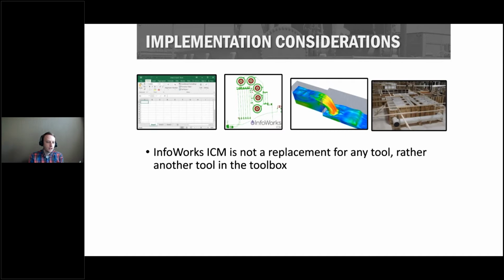I've got 4 here, but there's probably more. Oftentimes we'll do hydraulic design with a spreadsheet of some sort. There's also more sophisticated stuff like CFD modeling, or even, like this far right image shows, physical scale modeling. Where you want to deploy these different technologies might depend on how complex the design is and how much risk in the design you're looking to mitigate.